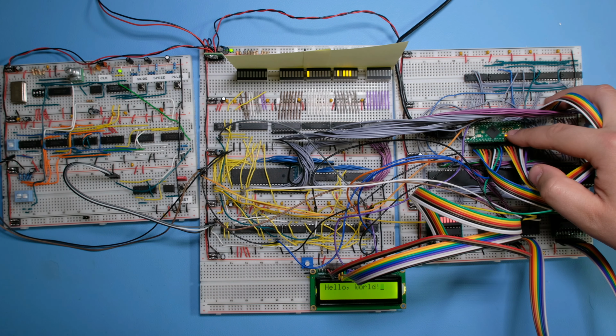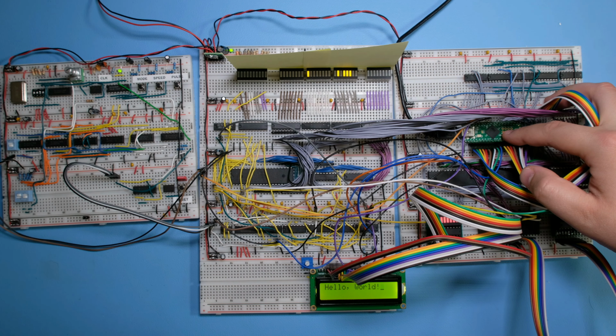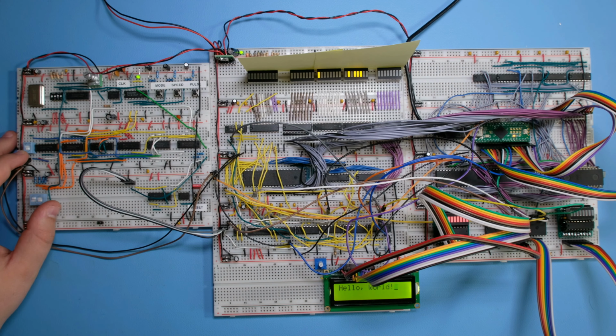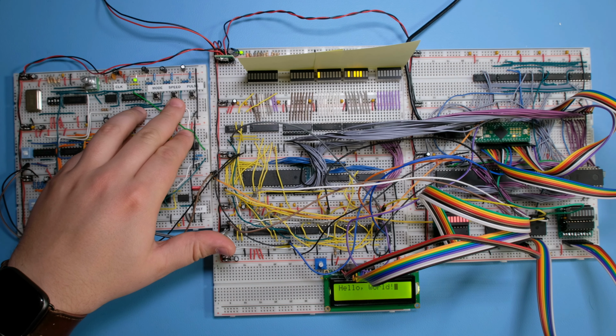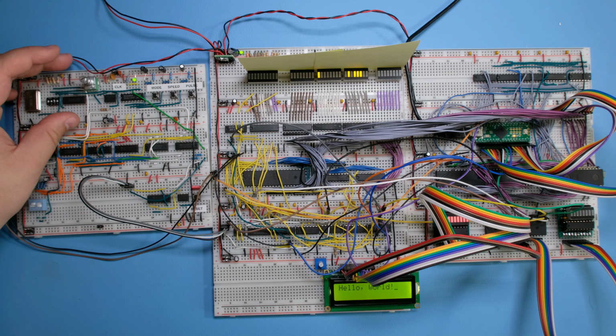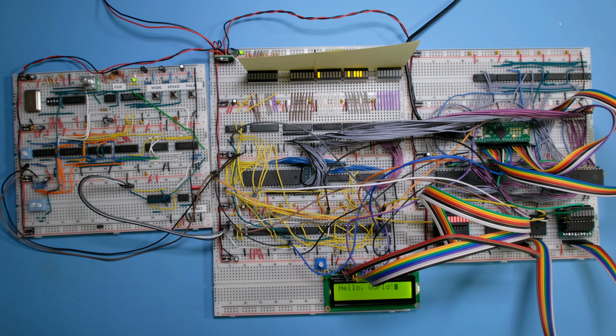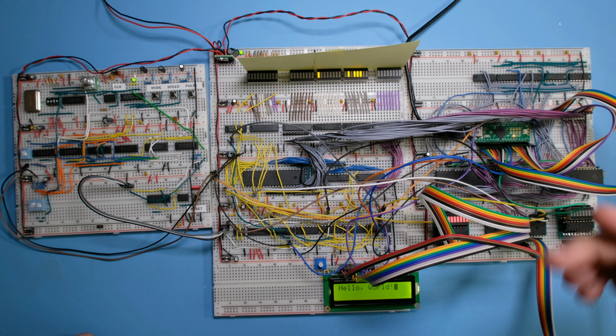And the first use of these new pins that I will implement today is I want to remove this switch in the clock here that I'm currently using to switch the slow clock from the built-in clock that is here to the clock generated by the Teensy. The way I want to do it instead is I want a control signal from the Teensy that can disable this clock module when I'm using the debugger.